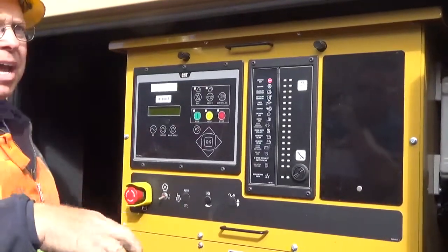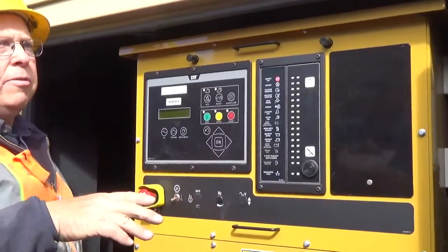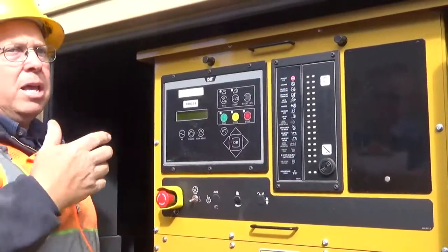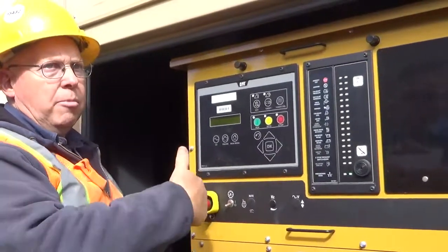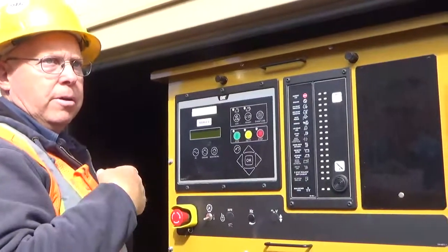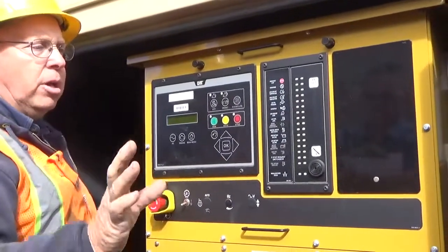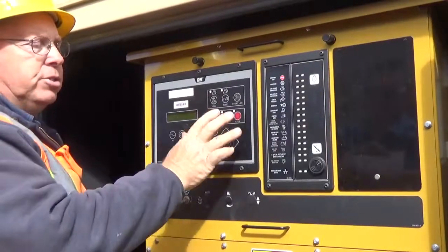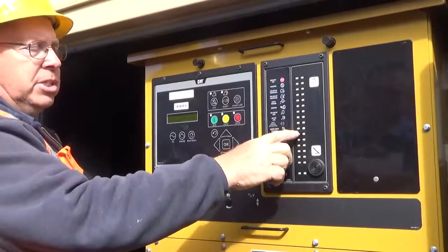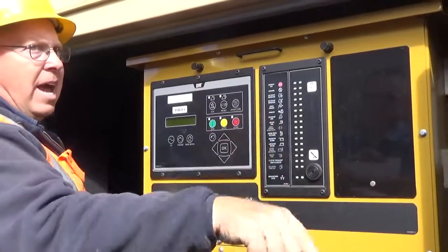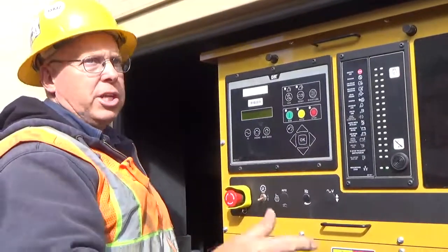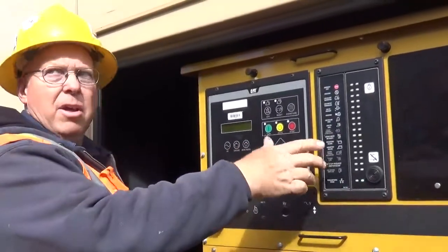The annunciators you have downstairs are a read-only device. So if you don't reset them, it doesn't matter to me. Down there will not send the alarm up here, like between me and the switchgear. So they're strictly read-only, but you cannot acknowledge those from up here. They're a different device. This is a CAN bus annunciator, here to here. Down there, it's RS-485.